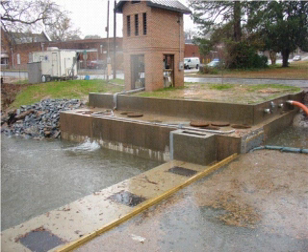But this kind of flow control allows a base flow to go through it, so fish can actually swim back and forth. But in this case right now, in Columbus, all the dry weather flow is being pushed through this facility and into the UV. This is the insert that goes into that flow control structure. It's a metal insert, and the bladder is connected to it. Water is on the top of that bladder that seals the pipe underneath and restricts the flow that can go through it, acts like an orifice, or it completely blocks that flow.